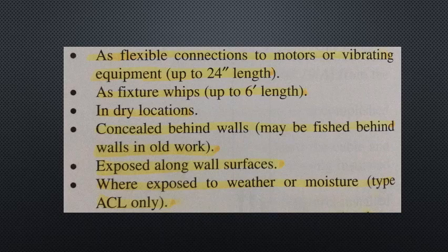The cable can be run along the sides of the studs, joists, or rafters without further protection. Guard strips made of 1x1 or 1x2 stock are used to protect BX or AC cable when it is run along attic floor joists.